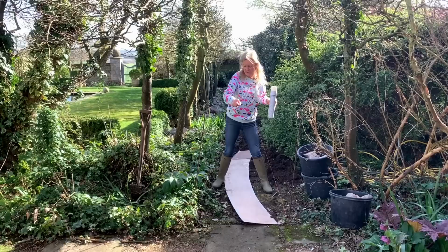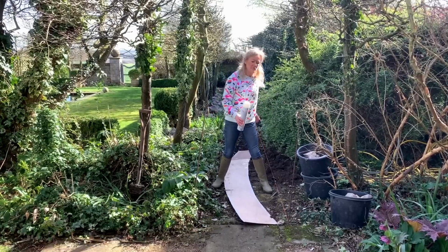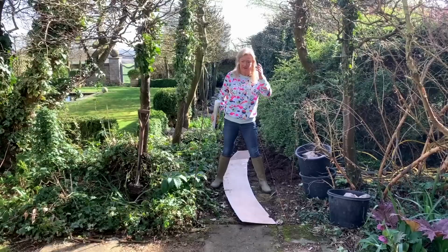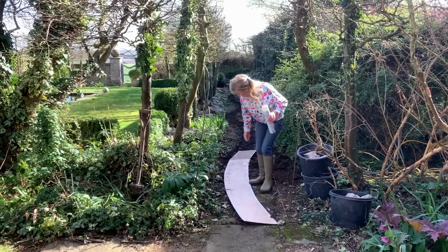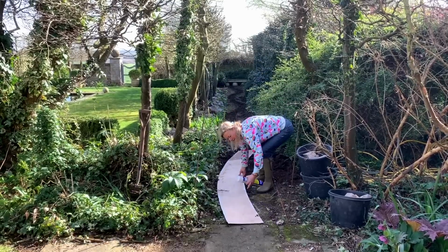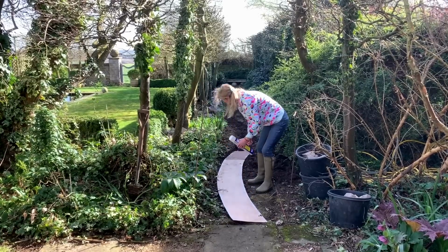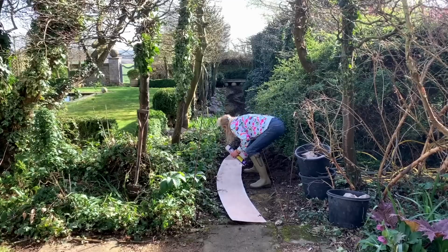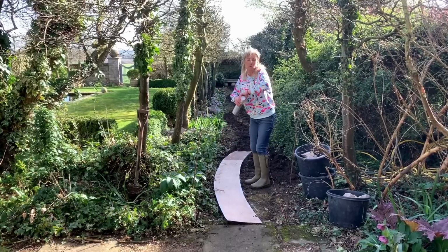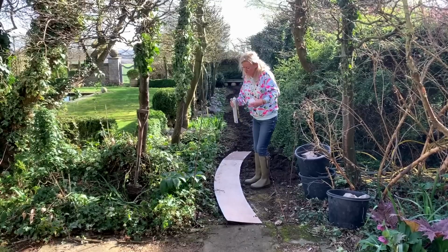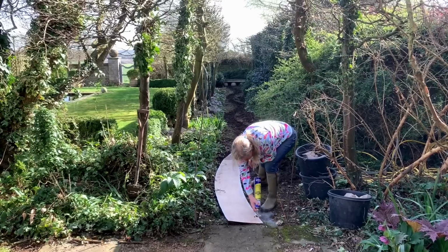So I put those 700 millimeters apart, and I've done the same at the other end, so I've got 2 parallel string lines. Having put this on the ground, the next stage is just to spray it out. I did this more accurately than I'm doing it now, but you just get the spray marker paint, or you can use emulsion paint and a brush, or whatever you like, and then you just spray it like that.